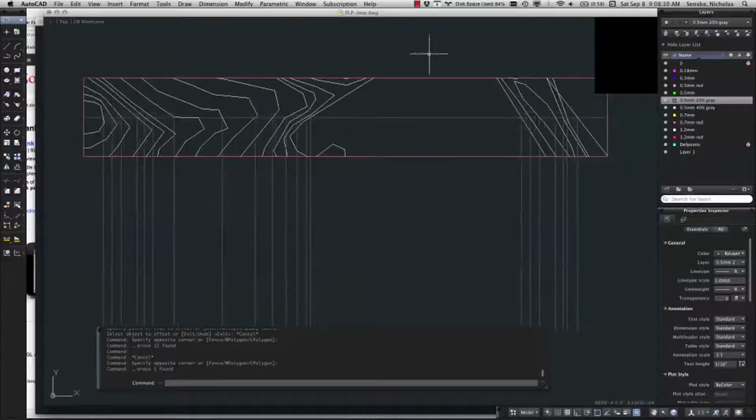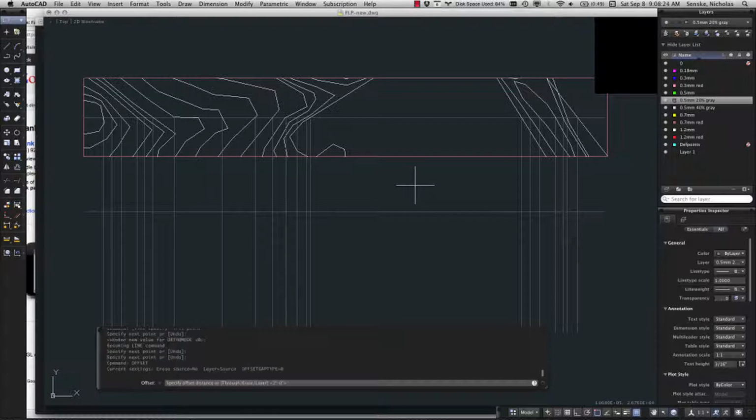Got this, the line set up. Go ahead and drop a parallel line. And there's different ways to do this. I'm going to see how this works for us, but I'm going to go ahead and offset that line by 2 foot, because these are 2-foot contours. Okay.